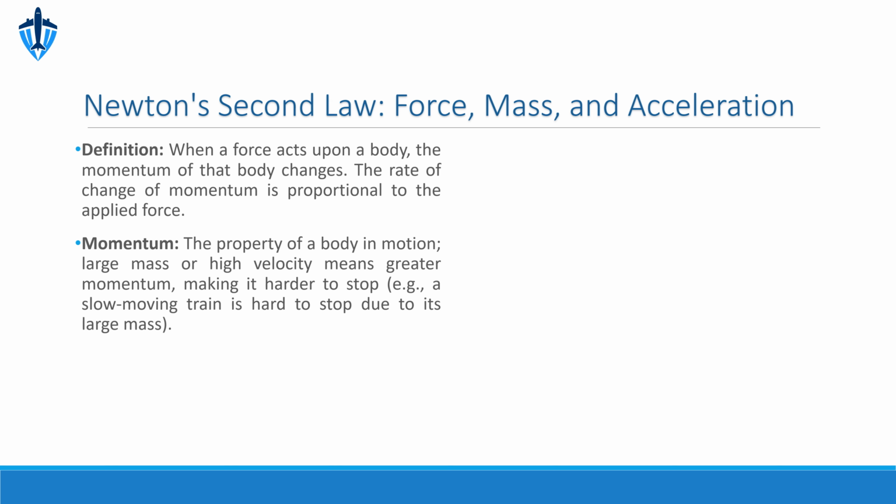Mechanical advantage, often abbreviated as MA, is a critical component in understanding how machines achieve their efficiency. It is defined as the comparison of the output force to the input force, or the output distance to the input distance. Machines serve to either multiply force, allowing us to achieve greater output than the input, or they can multiply speed, where one sacrifices force in favor of increased speed. However, it's essential to remember that a machine cannot multiply force and speed at the same time. Gaining one results in a loss of the other.